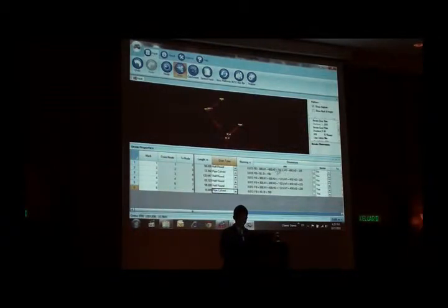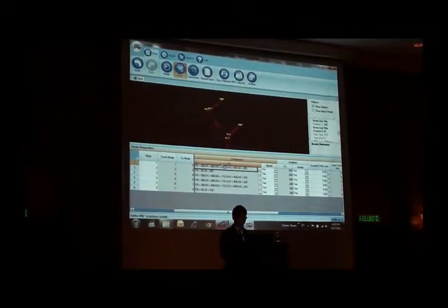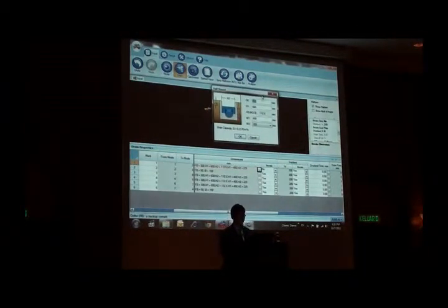After that, we also can edit the dimension for the drain. If I say iteration no, that means we can edit and change the value. Freeboard, H1. H2 cannot change because it's W2 divided by 2. We can change the W2 and the W1. When we change it, you can see the Q, the drain capacity, will automatically change.